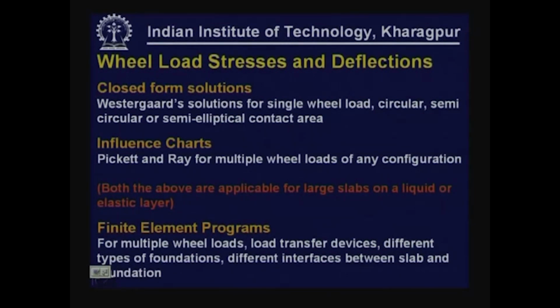So, using influence charts, we can determine the stresses due to multiple wheel loads and wheel loads having different contact areas. Both types of solutions, either Westergaard's analysis or influence charts developed by Pickett and Ray for multiple wheel loads, are normally applicable for large slabs placed on liquid foundation or spring foundation or Winkler foundation, or foundation being an elastic layer.